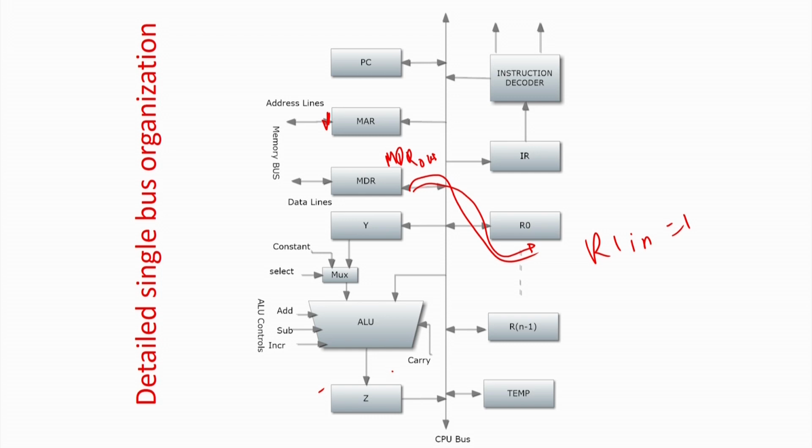So, the last 3 stages basically read the value of M from the instruction register, write it in the memory address register, wait till the value of M is dumped to the memory data register, and then MDR out will take the value from MDR and load it to R1. So, your job is done.